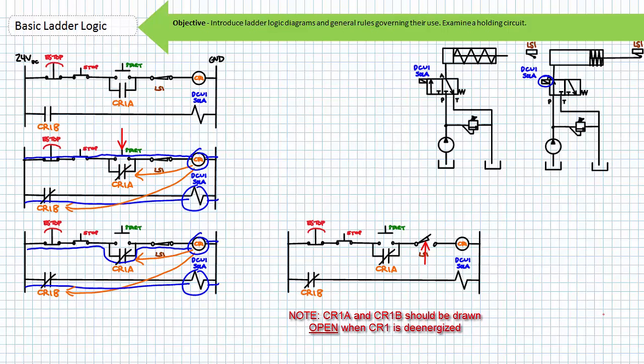Every time a new device or connection was made, this necessitated a technician physically rewiring the inputs and outputs to yield the newly desired functionality. In contrast, to change the functionality of an electrically controlled system employing a PLC, one must simply reprogram the system. This is to suggest that an electrically controlled system employing a PLC is significantly easier to install, modify, and troubleshoot than those employing traditional hardwired relay-based ladder logic.